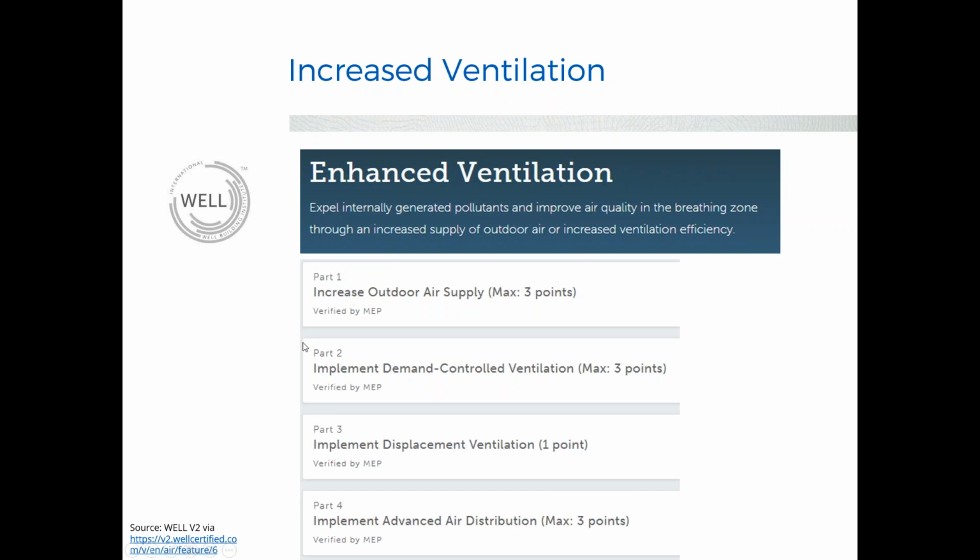And then we have other strategies too that you can implement, like demand controlled ventilation, which is quite common in office buildings. But under this new feature, you get rewarded for the carbon dioxide concentration, and with a reduction in the set point, say from 900 ppm to around 600 ppm, you get additional merit for reducing the carbon dioxide in the space.